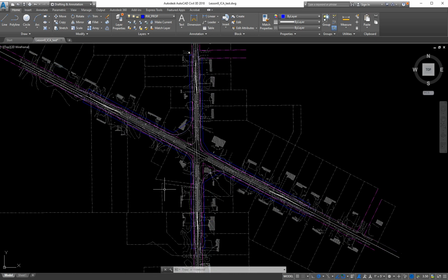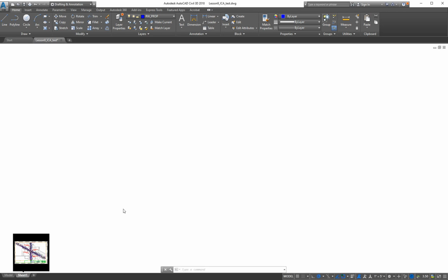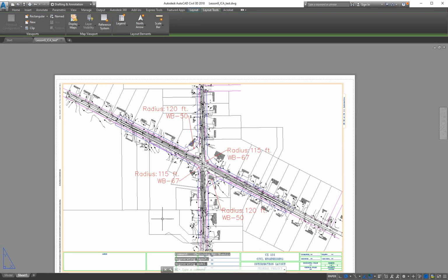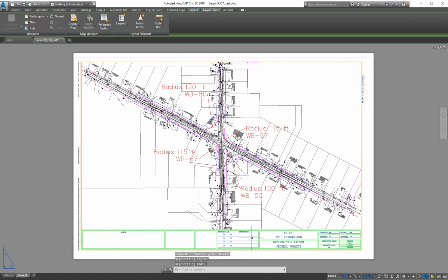Paper space, as the name sounds, means that's the sheet. All right, so let's flip over to that. Here's sheet 1, right? It even calls it a sheet. That's its default name, and this looks like the title block, right? When we did this before, we used the title block as a block inside model space. We put it into our normal drawing, and that's not where we normally put it. We normally use a title block like that in a sheet file in paper space.